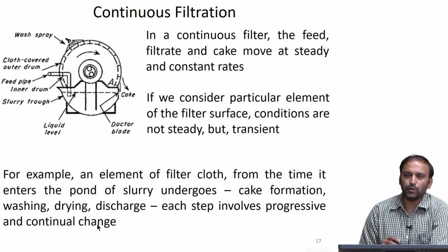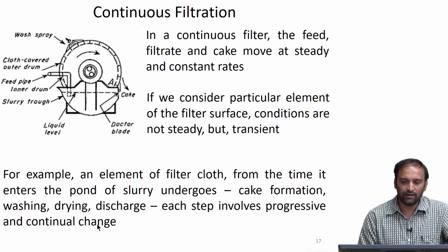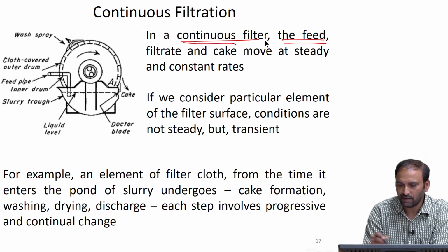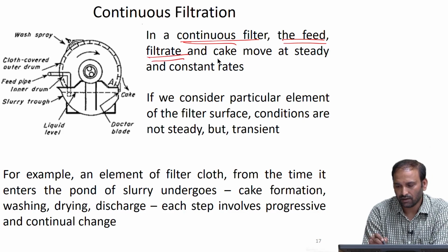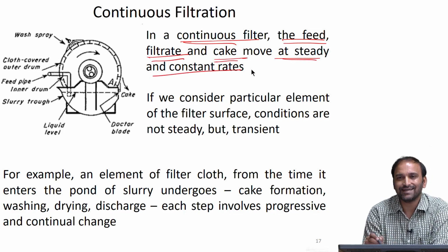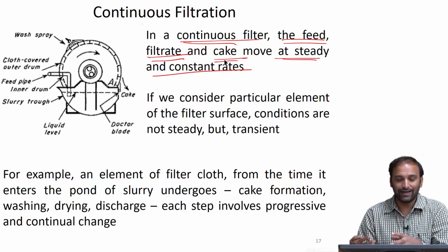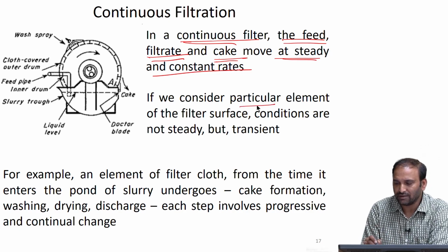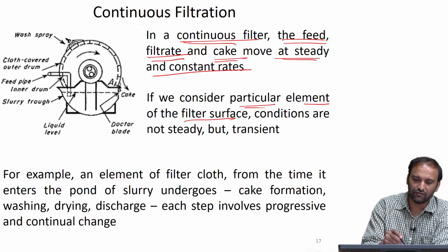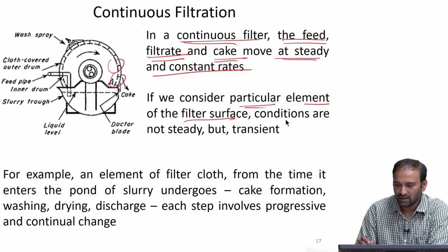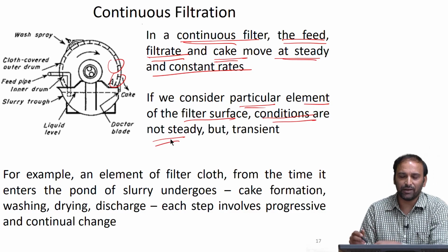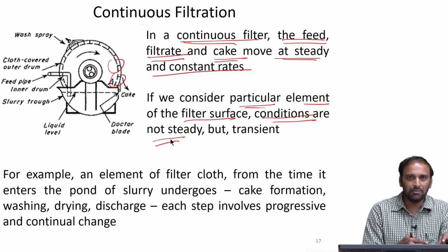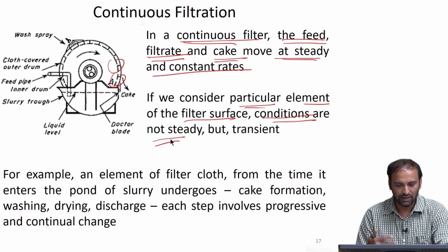So, therefore, what we can do is actually modify. If you look at the continuous filtration process, the feed, the filtrate, and the cake all move at a steady, constant rate during the entire course of filtration. But if you consider a particular element of the filter surface, that means if I take these different panels, the conditions are not steady but transient, because some are undergoing cake formation, some the washing process, and some the cake removal process.